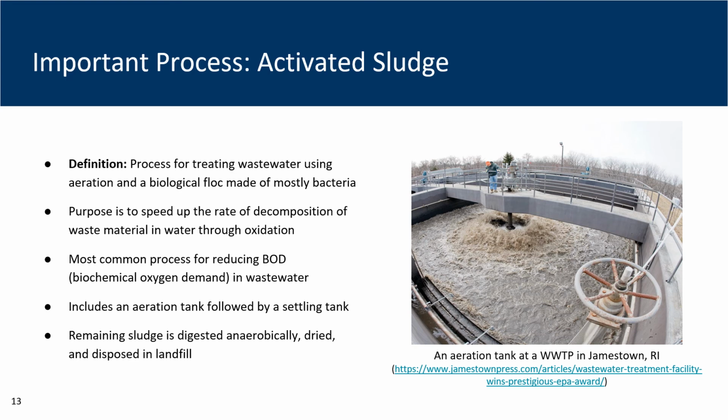The organic matter in the wastewater still represents a high demand for oxygen, which must be reduced further so that the effluent can be rendered suitable for discharge into a body of water. The biomass uses the BOD in the wastewater as its food source and requires a very controlled environment, including a sufficient food source in the form of the BOD and adequate oxygen in order to survive and replenish. As for the organic material, it is removed from the wastewater through the work of flocs of bacteria, which are suspended and mixed with wastewater in an aerated tank.